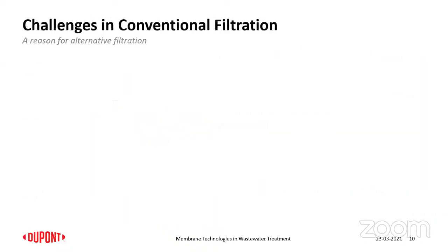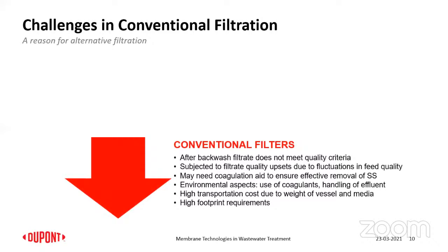And not just this, there are more challenges in conventional filtration. So I was talking to you about change in the feed quality, change in filtrate quality based on the feed quality. After a cleaning process, the filtrate also does not meet filtrate quality. This is a very standard problem that you would see in many pressurized or depth-based sand filters. Like I said, the filtrate is subjected to filtrate quality upsets due to fluctuations in feed quality. This is what we saw on the last slide.